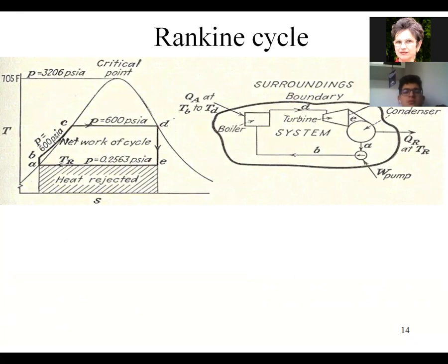So the Rankine cycle is running with water. So we have A, water, B, water, but A is low pressure water. When it enters the pump, here is A, here is the same A, yes? B, when the water enters the boiler, the water is heated, then it is turned into vapors. So D is going into the turbine, the exhaust is E. So this A, B, C, D, E is a Rankine cycle with saturated vapors.